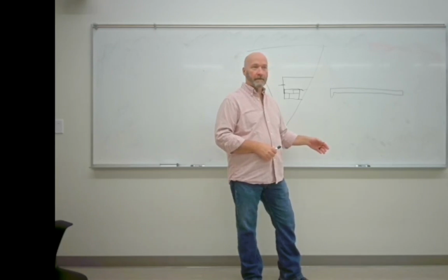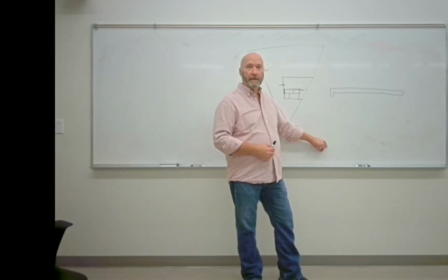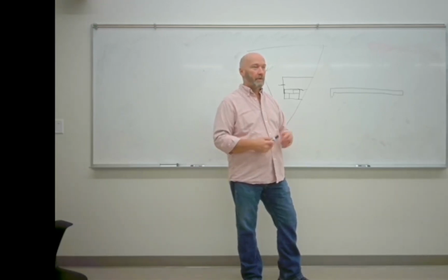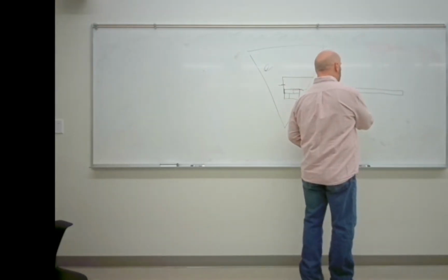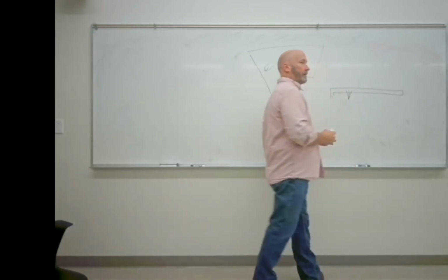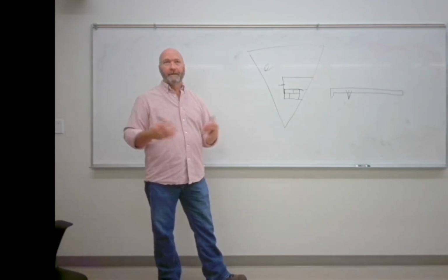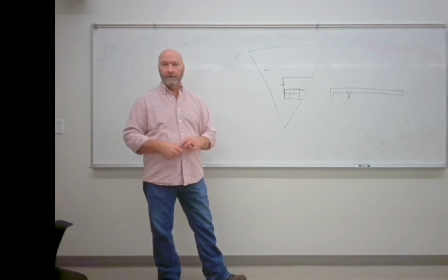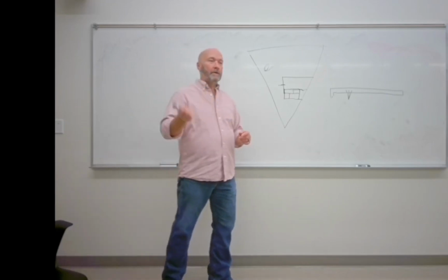So touch it, nothing. Touch it again, a little bit slower this time, nothing. Reach over and grab it, and I can feel just the slightest tingle. Like, okay, I got a short somewhere. Because what happens in a short circuit on an electric fence, most of the time, is grass has grown up. Okay, what's grass? It's a preferred weed, but it's wet, right? Except for now, it's pretty dry, but it's full of water. So is water a conductor, or is water an insulator?